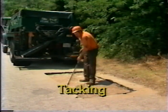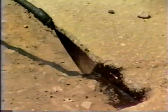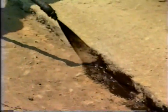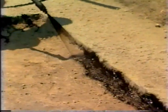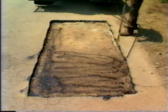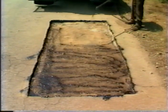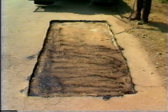The hole is now ready for the fourth step in the patching procedure, tacking. A tack coat is a thin layer of liquid asphalt which provides a bond between the old and new materials. Tack the bottom and sides of the patch area in an even thin coat. Too much tack will soften the pavement and cause bleeding or shoving of the patch. Too little tack will result in a poor bond.